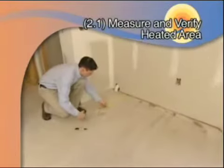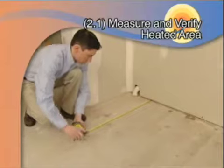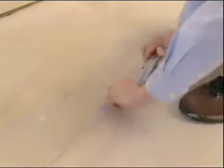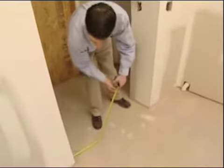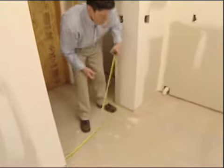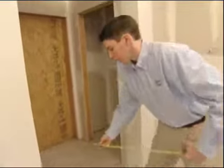First, calculate the walking traffic areas for your warm tiles installation, referred to in this video as the heated area. In a new room like this kitchen example, measure and mark out all of the fixtures from your room design or blueprints, such as cabinets and appliances, on the floor area. The walkable square footage of the room is measured and calculated by breaking the heated area into simple shapes.